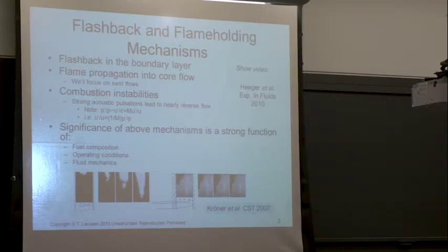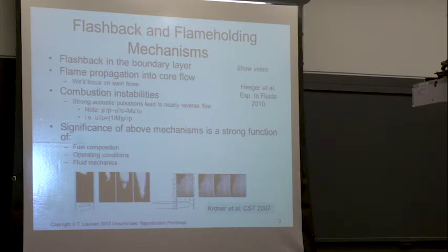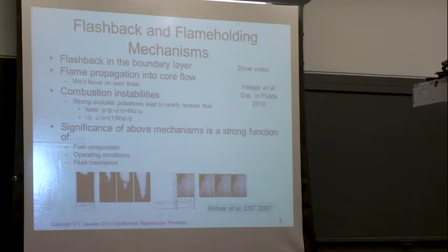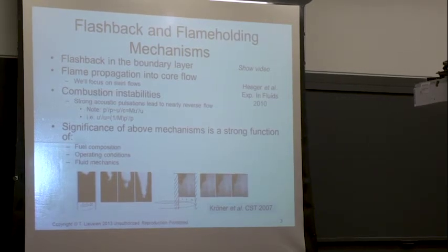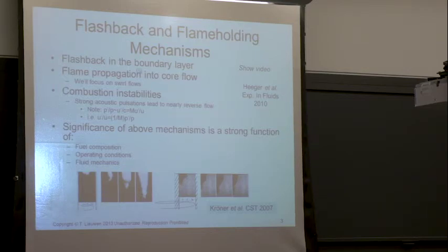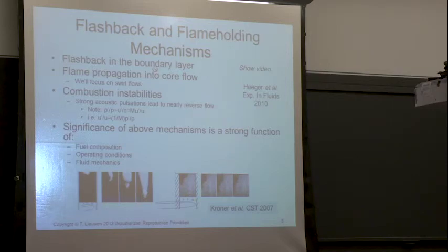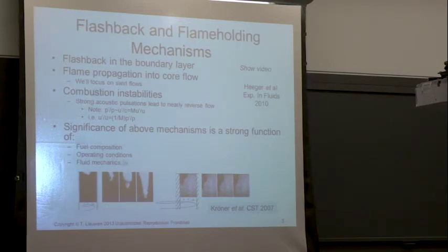meters per second. Or even if you get a violent thermoacoustic instability, the flow can actually reverse itself. So the flow is actually going backwards, maybe negative 10 meters per second. It's sucking the whole flame upstream. And when it gets sucked upstream, it starts melting stuff. So the problem of combustion instabilities and flashback is very much coupled. And these are really interesting problems because they have different sensitivities to your fluid mechanic features, to your fuel composition, to your operating conditions.